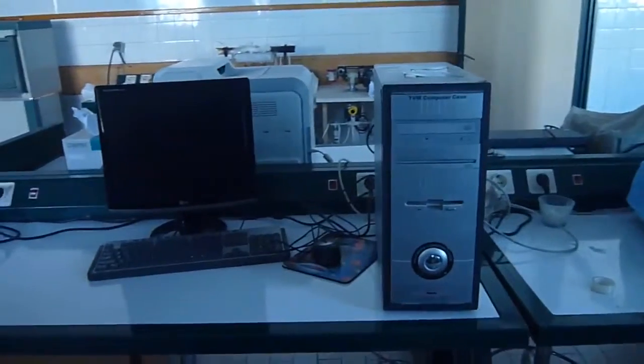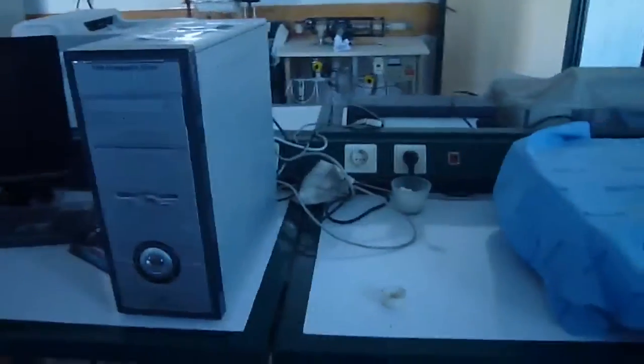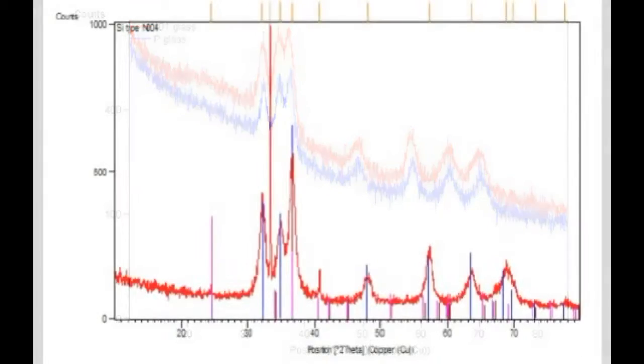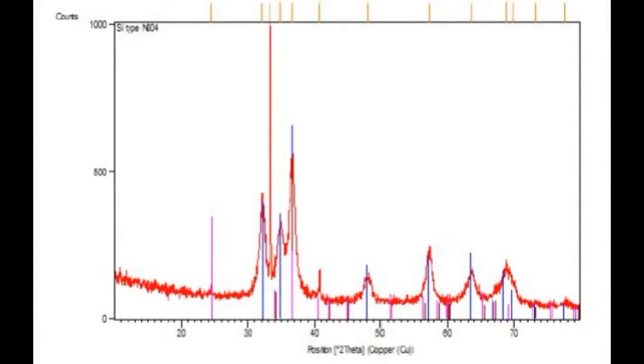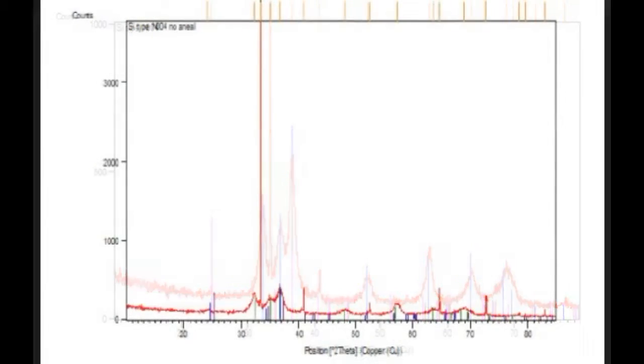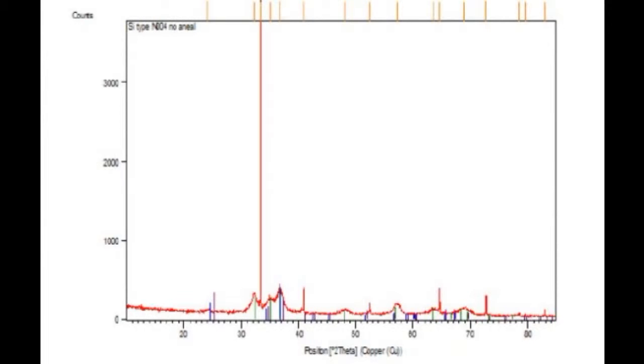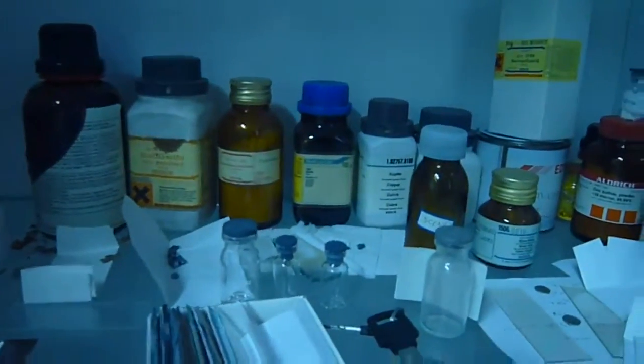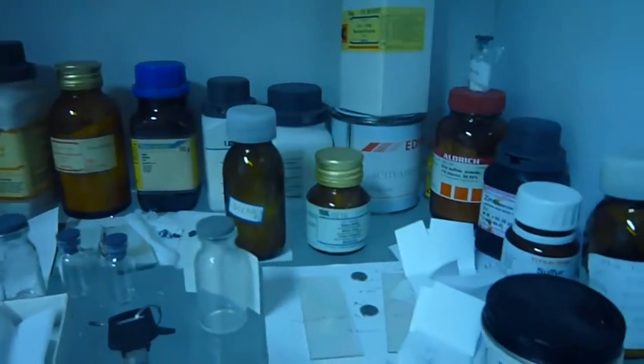Annealing occurs by the diffusion of atoms within a solid material so that the material progresses towards its equilibrium state. Heat increases the rate of diffusion by providing the energy needed to break bonds. The movement of atoms has the effect of redistributing and eradicating the dislocations in metals and, to a lesser extent, in ceramics. These alterations to existing dislocations allow the metal objects to deform more easily, increasing their ductility.